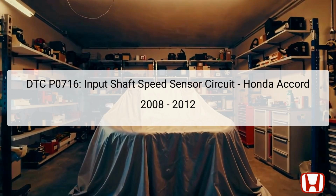In this presentation, we will diagnose DTC P0716, which indicates a problem in the input shaft speed sensor circuit, specifically for the 2008 to 2012 Honda Accord. This trouble code suggests that there is an electrical issue related to the signal that the input shaft, also called the main shaft, speed sensor sends to the engine control module, ECM.